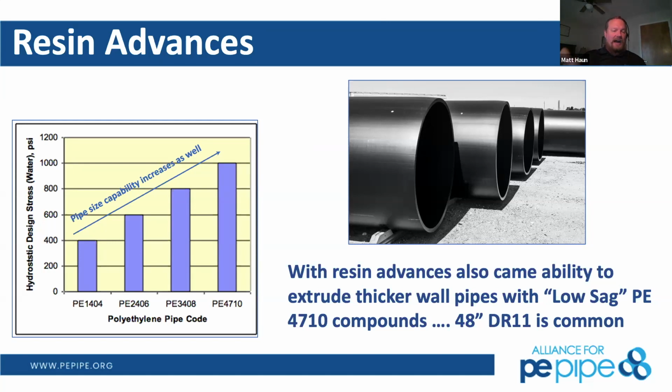So whether that's higher hydrostatic design stress to account for thinner walled pipe meeting higher pressure ratings, or maybe it accounts for installation methods requiring a little bit more precision to withstand the environments that they get installed in. That's the kind of improvements that you'll see by that chart.